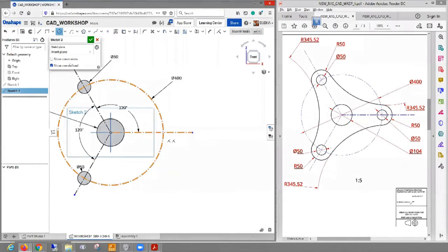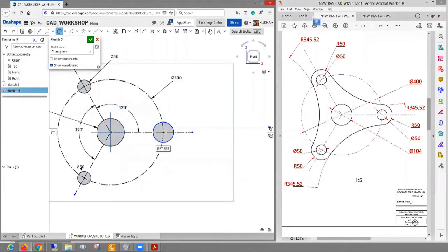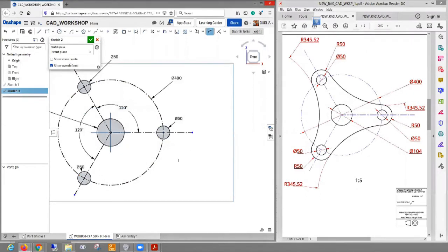southeast of the mouse, you will see that there are 2 small icons showing up. That means that's a coincident icon. So you see that this particular icon, coincident, is showing up. There's 1 and there is 2 coincident buttons. That means the point I am selecting is coincident on both the construction lines. Now let's change the dimension to 50.